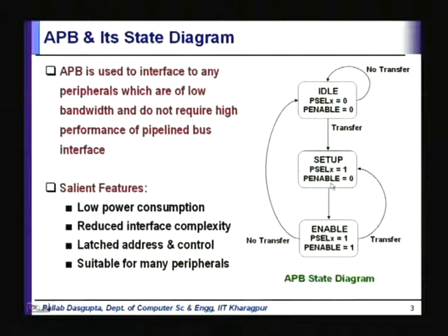So, that is the setup phase, and then it will raise the PENABLE, which is only one signal, it is not PENABLEx, PENABLE is one signal. It will raise that, and that is going to initiate the transfer. That will initiate the transfer of one data item, and then it can go round and round in this loop several times to transfer several data items, for the same device. And then when it is done, it is going to lower both PSELx and PENABLE and go back here,